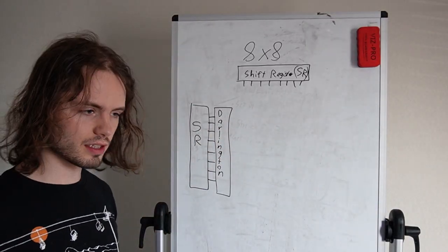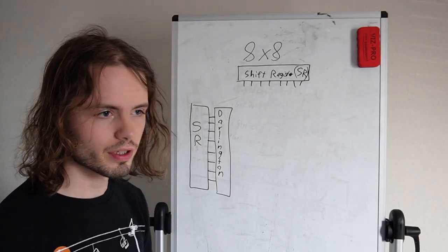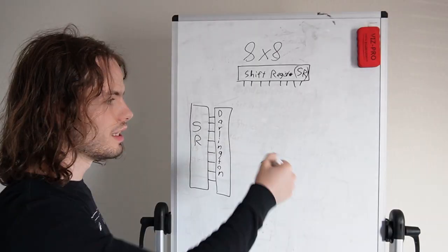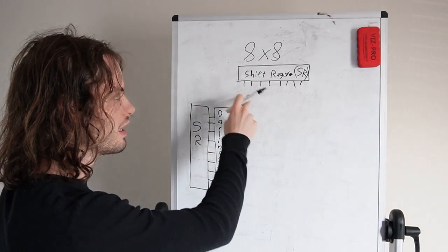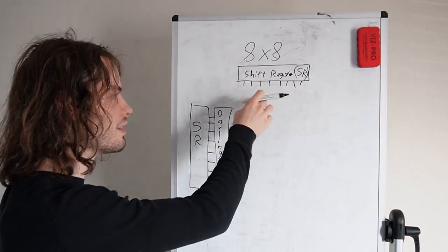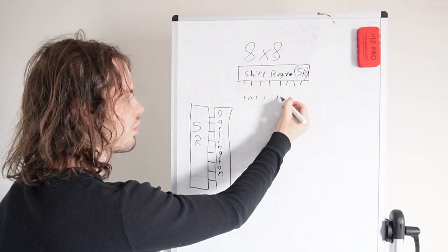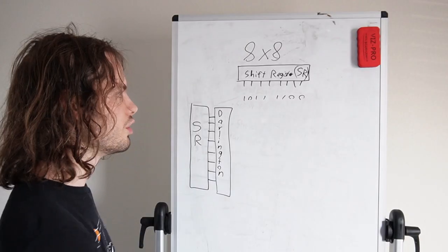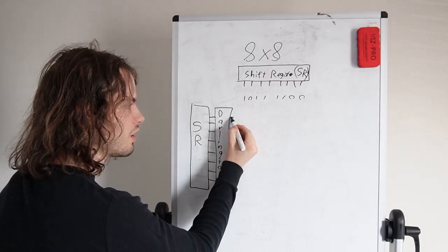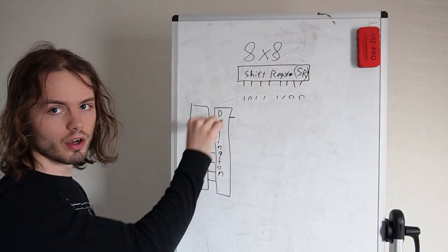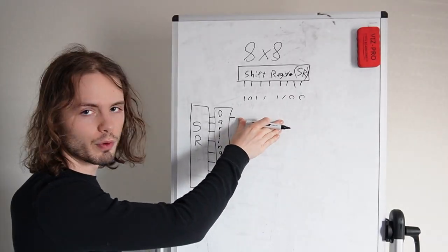The idea is that an image, if you break it down into pixels and assume the pixels are just on or off, is a 2D array. So you can shift in the first row of data into this top register. If the first row of the image is 1011 1100, something like that, you would load that information into this register up here, and you would turn on this first row on this shift register. That way, current can sink only when row 1 is on.